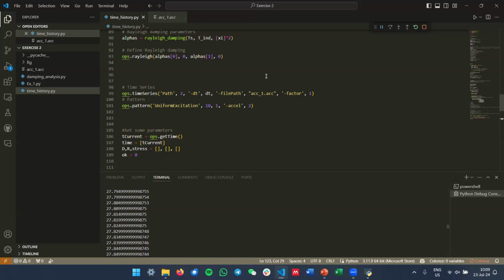I think the easiest way is, for each load increment, I save the input OpenSees Python file separately and run it separately, take out the load effects and work accordingly. Then you write another script for the post-processing to read all the results and do whatever you want with that.